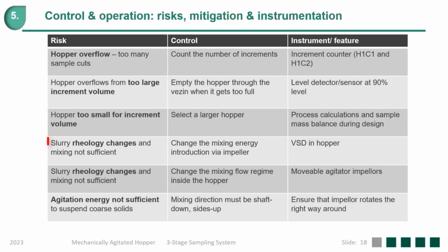Another risk is slurry rheology changes and mixing not being sufficient. We need to change the mixing energy, via the introduction of air or via impellers. The instrument that can be used is a VSD in the hopper. We need to install a VSD in the hopper.